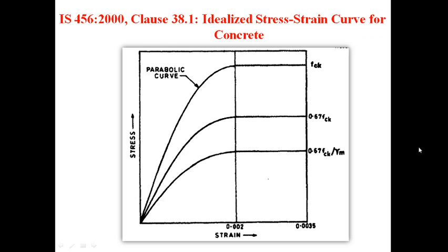But if you look at the site, when you actually do concreting for a column, beam, or any element, then the load applied is not short, it is for a lifetime, it is a sustained load, and moreover the size is more, and there is a quality control issue. Therefore concrete technologists across the world said that the strength of concrete on the site in any structural element divided by the strength of the cylinder in the lab is normally 0.85. Then why is it 0.67? Let us discuss further.